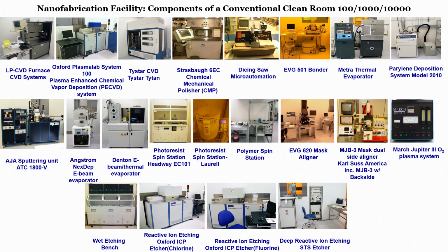The next one is a PECVD, which stands for plasma enhanced chemical vapor deposition. This is used to grow silicon dioxide and silicon nitride, but the advantage of PECVD over LP-CVD is that the temperature used for the reaction is very low, about 400 degrees centigrade, and in LP-CVD I was talking about 1100 degrees centigrade. Now, why then do we have to use PECVD if LP-CVD can be sufficiently good for us to grow oxides? Why is low temperature required?